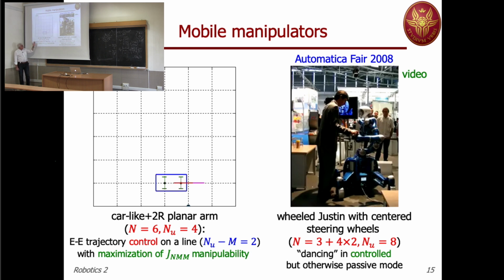So now we look at the task. The tip of the manipulator, something that lives on the plane, should follow a trajectory. Here you can hardly see a point, which is the starting point of the trajectory. This trajectory will be a straight line going across the workspace. So initially, the robot is placed in this condition. And in fact, the end effector is not on the initial value of the desired trajectory. So our scheme should include the presence of an error.